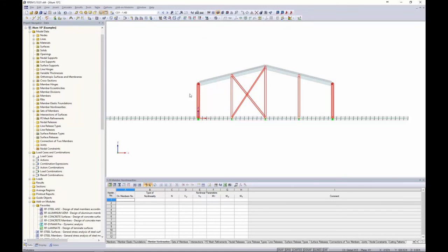Now, geometric imperfections really are to account for a column out of plumbness. There are some other stipulations that you can maybe add in, like pre-camber, which we'll see in just a minute, but for today we're really concerned with column out of plumbness in terms of geometric imperfections.